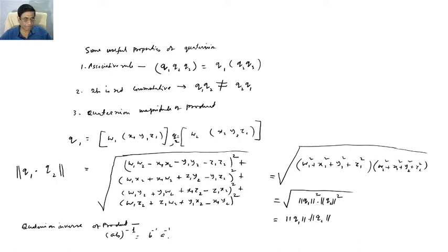If there are many operations like quaternion Q1, Q2 up to Qn, the inverse of that will be equal to Qn inverse, Qn minus 1 inverse, and so on up to Q1 inverse. So in the reverse order, the inverse of the product is the product of the individual inverses. So these useful properties are exploited extensively for capturing the orientation.